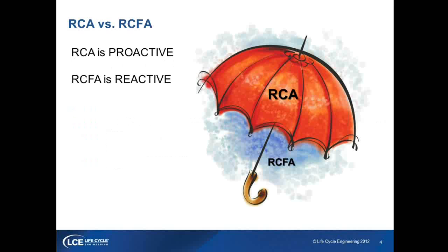When we talk RCA, root cause analysis, it can be either proactive or reactive. The way I like to think about it is that RCA is the overarching umbrella, and RCFA, root cause failure analysis, is a subset and a part of that. So if I have a pump failure or a transformer failure, I can conduct an RCFA to determine what the root cause was, develop corrective actions to remediate that cause, and then move forward and ensure my actions address the problem at hand. Whereas when we talk RCA, that's really the overarching umbrella.